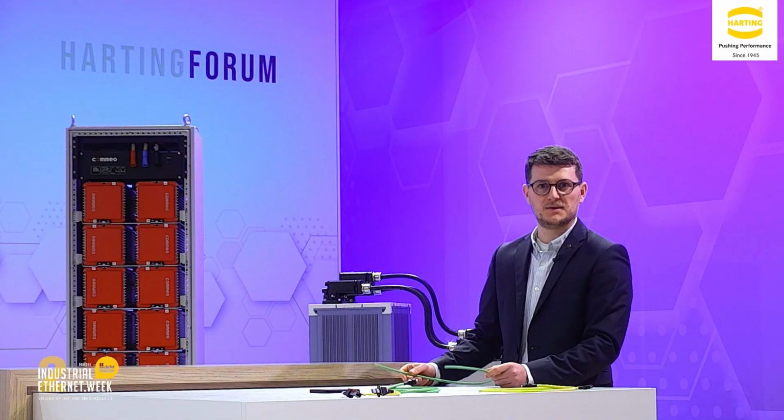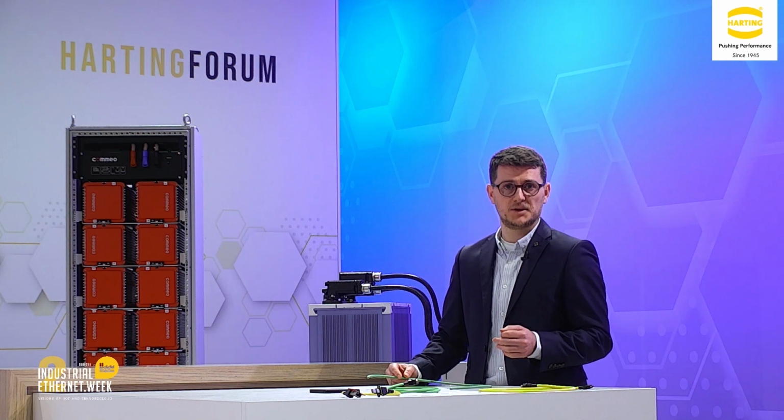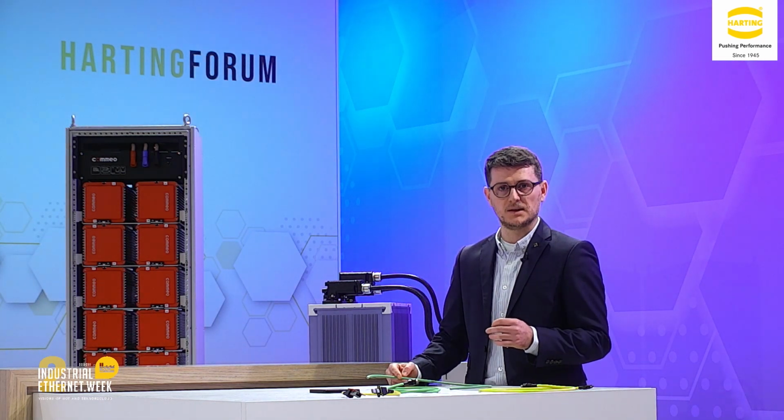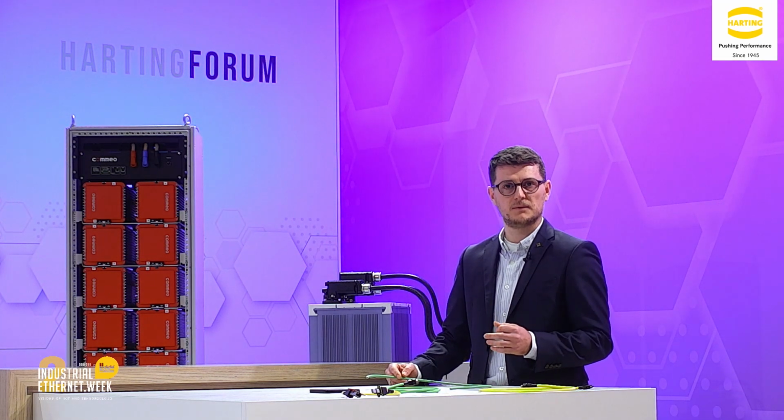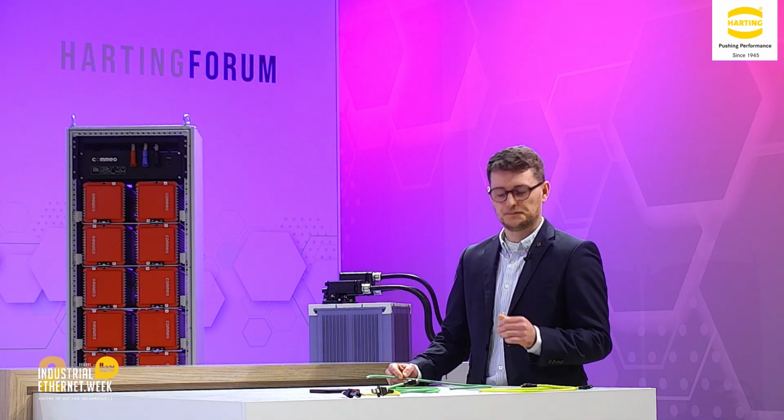Thanks, Jonas. So pretty nice to see the wide range of our portfolio next to connectors and plug-and-play solutions. We're also offering the raw cables. As Jonas mentioned, we have different kinds of requirements, right? And the HARTING Profinet cables are specially designed to meet the requirements of different applications. We have several movements, and we have fixed installations. And what does it mean in detail? We have the types B, C, and R for movements, for flexible use. And we have the type A for fixed installation.